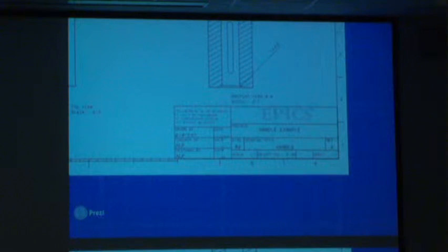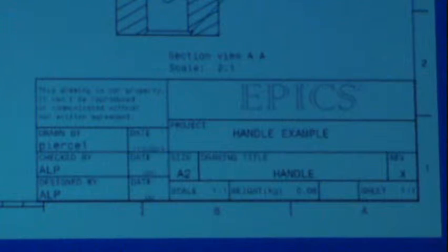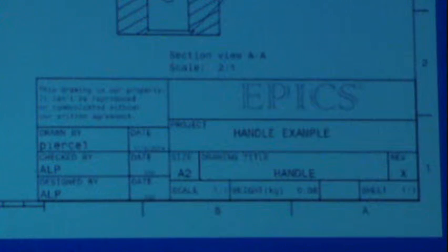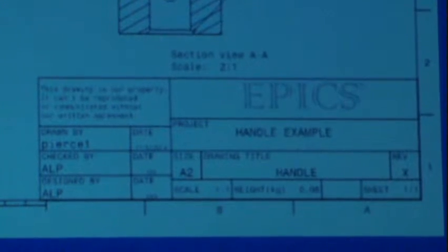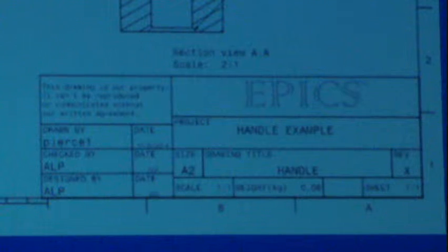There's the title block we talked about a little bit, so you can see you indicate who made the part, what the part was, and then the part revision. So part revision is very important. As you update or change the part, people can tell what version you're referring to. So when you put this part into an assembly, you may have built your assembly with the revision A, and the part may get revised 2 or 3 times and may simply not be updated, and then you can run into issues.